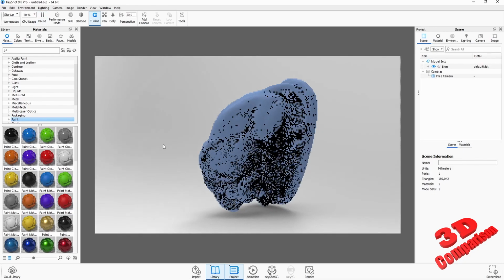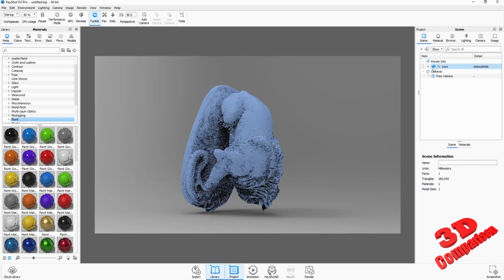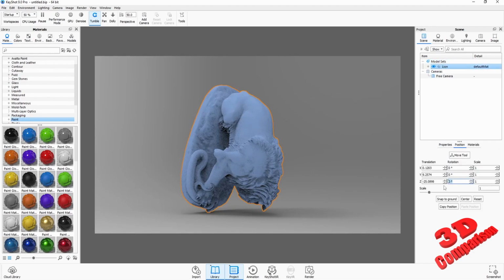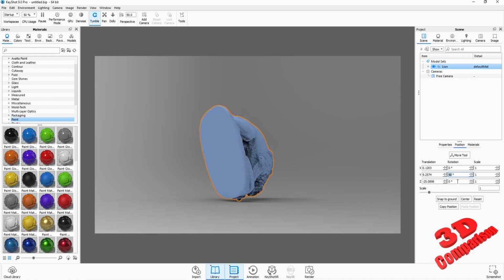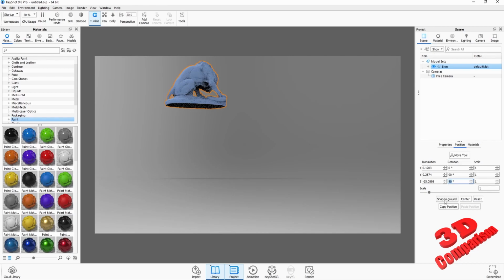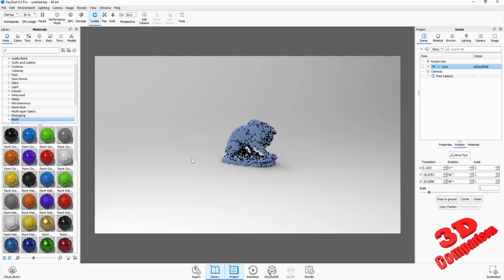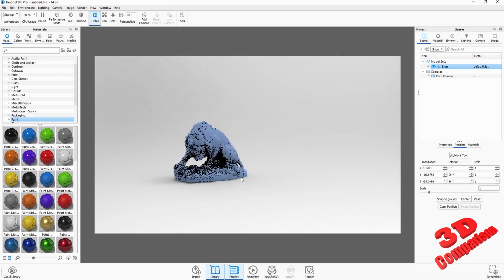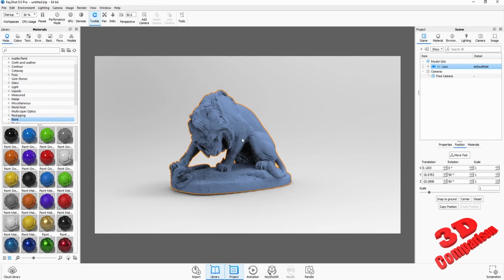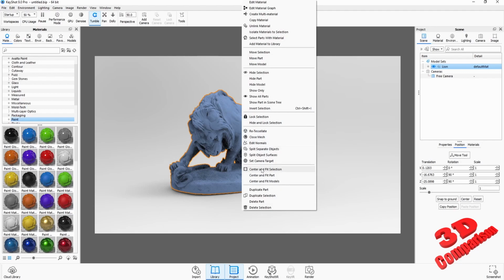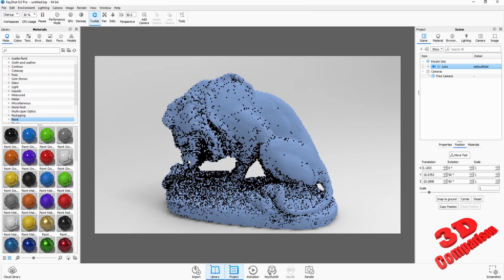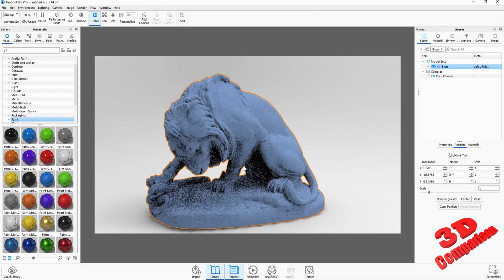We're gonna see how the model will be positioned within Keyshot. It will need to be realigned. So let me just rotate this, let's see, on the z-axis. Afterwards, snap it to the ground. And now we're gonna have that positioned. If you wanna center on the object, you can go over here with right click, set camera target, and afterwards you will be able to rotate around the model.